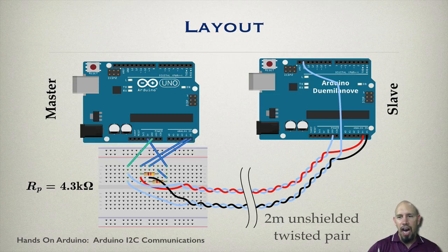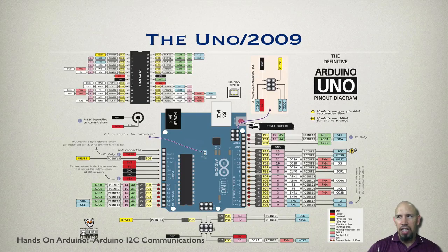Well, in case you have forgotten, we're going to take a look real quick at this diagram of the Arduino Uno pinout. And we see that A4 and A5 have as an alternate function SDA and SCL, so the data and the clock. Now, the Arduino Uno actually has the clock and the data over on this side as well, in these 2 pins.